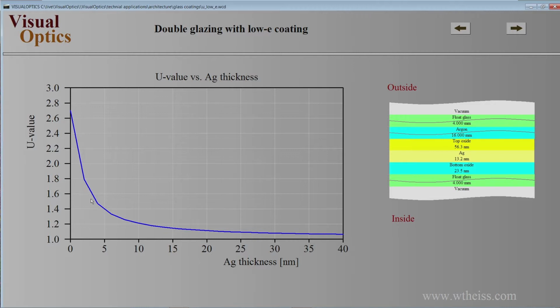It's almost exactly the same. So the transparent oxides do not disturb the good low emission that we achieve with our silver layer. So that's the good news. We can play with colors without damaging the thermal properties of the glazing.